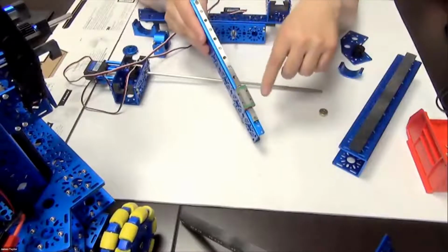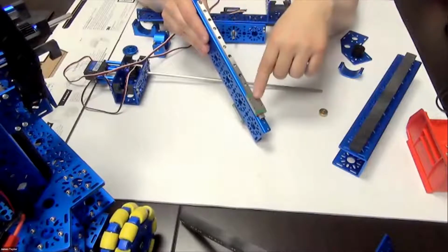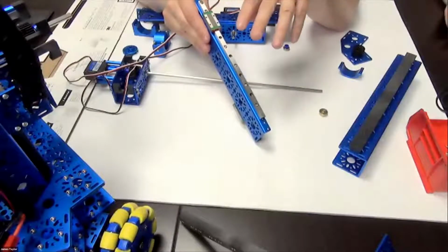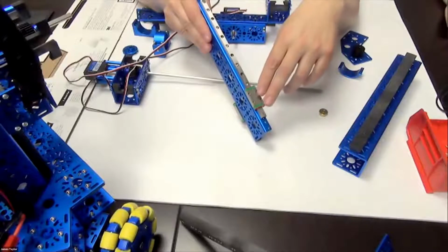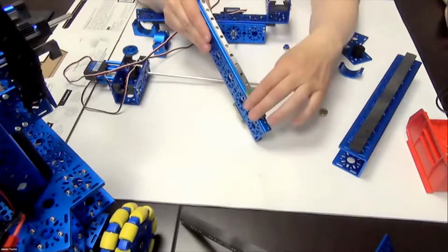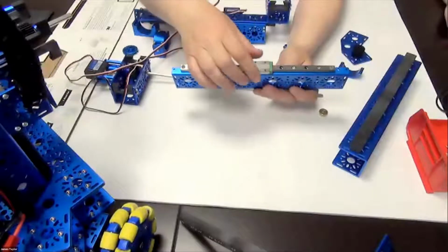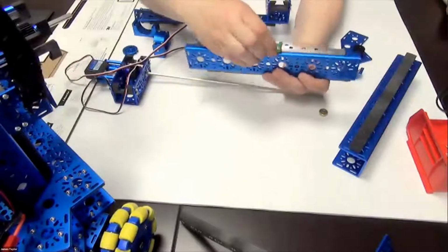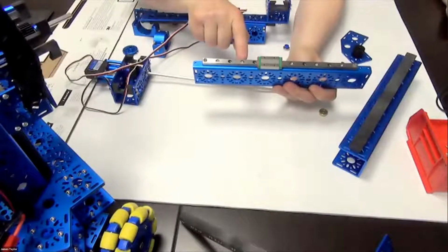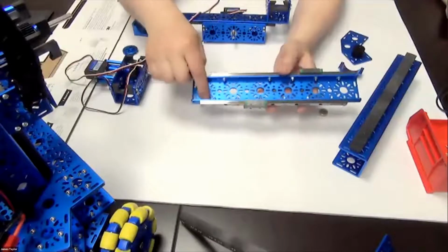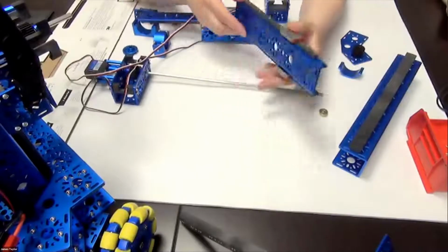These do come packed in grease, so you may have to clean them out a little bit to get a nice smooth slide, because as they get put into shipping, they can gum up. We just use a little bit of WD-40 or a little bit of oil solvent in there, and then you'll get a nice smoother slide. As I said, these will constrain the movement in one direction. When mounted, they're very, very sturdy, and you won't get a slide. And we've just mounted this with our M3 socket head cap screws right to the slide mount here. So this one has two 250 millimeter slides on it.